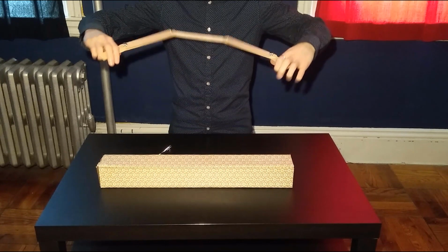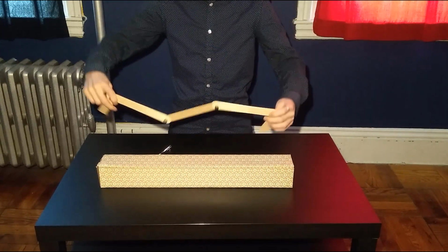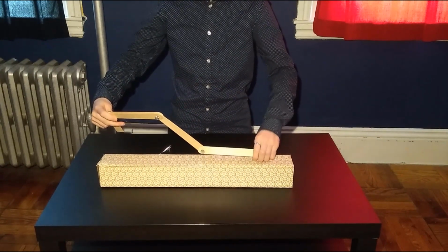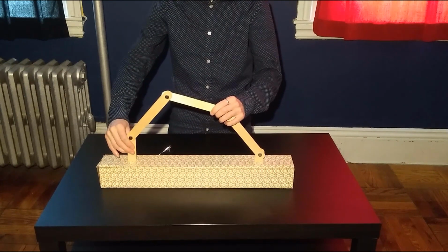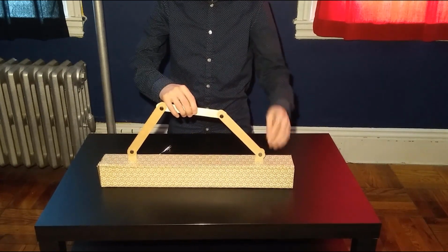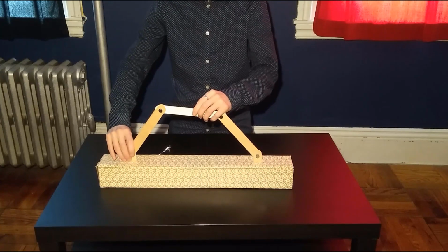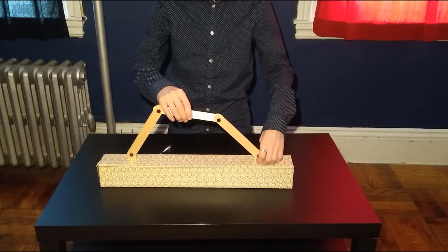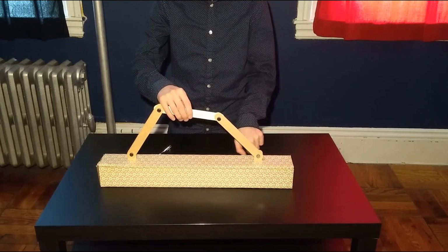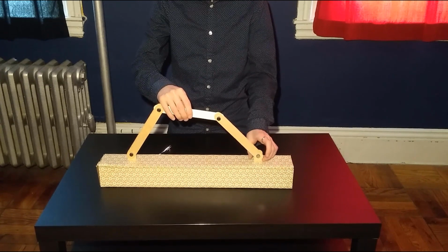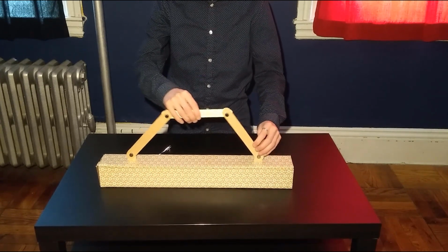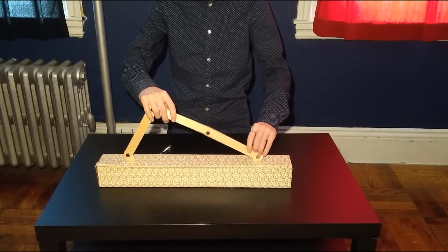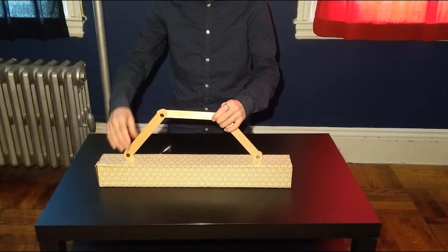And if I flip it around like this and place its ends into this cardboard here, so I'm applying some boundary conditions, and these would be pinned conditions because I'm giving a vertical reaction against gravity. I'm also providing a horizontal reaction against the thrust of this arch, but there is, again, no restraint against rotation at this joint. And so it is a pinned end.